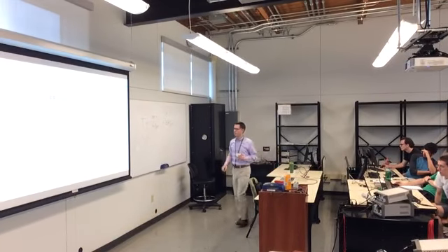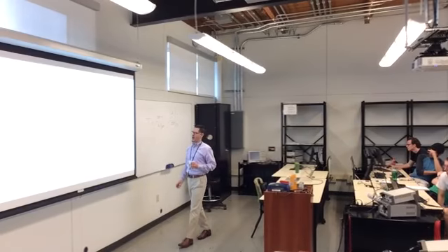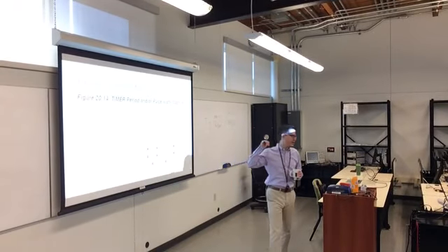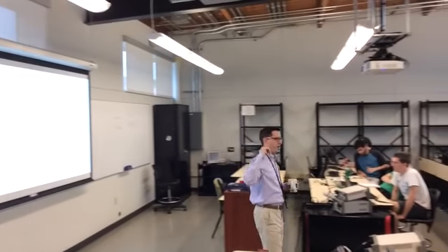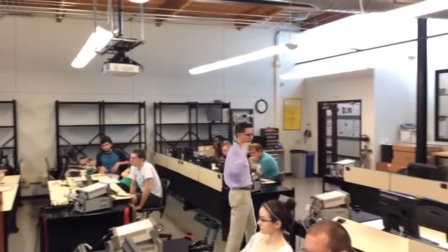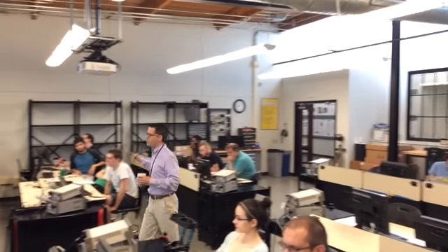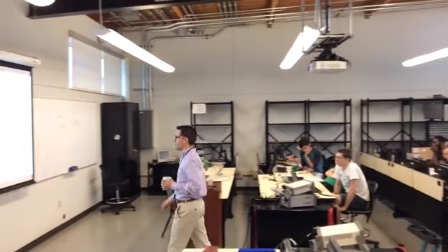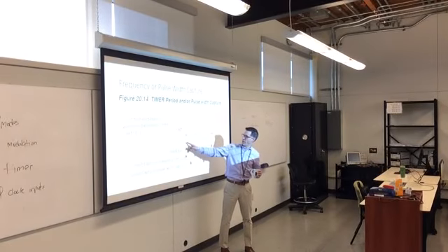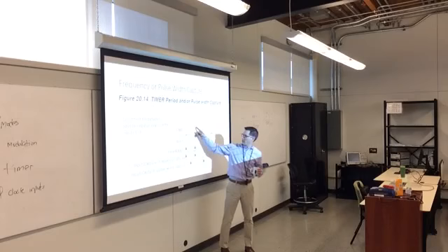Final thing: the previous example was generating an arbitrary wave. Here you may want to capture and measure an arbitrary waveform. You want to know how long a signal is high, how long a signal is low. There is a mode called clear and start, and what happens is when there is a rising edge, the timer begins to count, and it counts until the next rising edge.